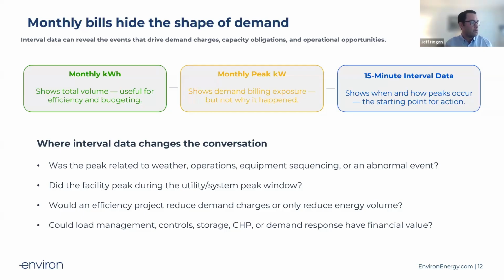I think I would just add, when we're talking about load management, maximizing the value of the assets that you have on site. Sometimes a hospital is maxed. Maybe this summer, you might have barely met the cooling need. But if you do have hybrid plants, chiller plants with assets of different vintages from different years, they all have different efficiencies. And if you haven't looked at the way in which you can sequence those operations to achieve that peak load in the most efficient manner, there are ways that you can flatten that load profile.